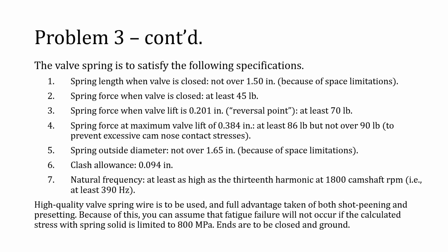Yeah, so we have high quality valve spring wire that we're going to use, and full advantage taken of both shot peening and presetting. Because of this, you can assume that fatigue failure won't occur, so we don't have to worry about fatigue, as long as the calculated stress with the spring solid is limited to 800 megapascals. And when we're doing our calculations, we have to keep in mind that the ends of our spring are to be closed and ground.